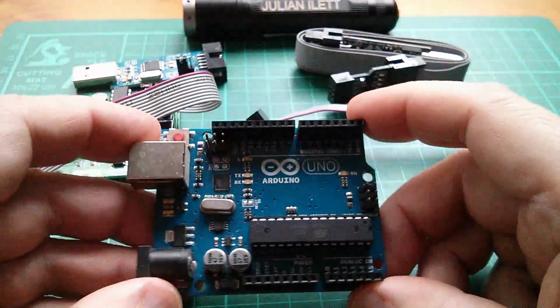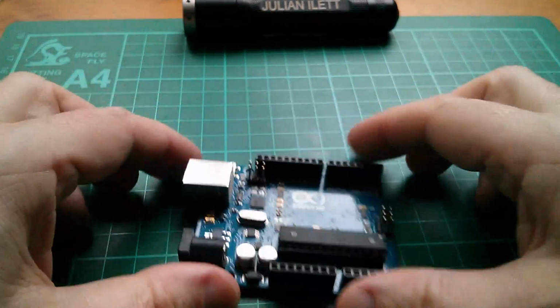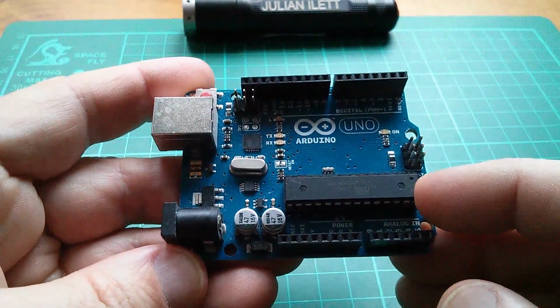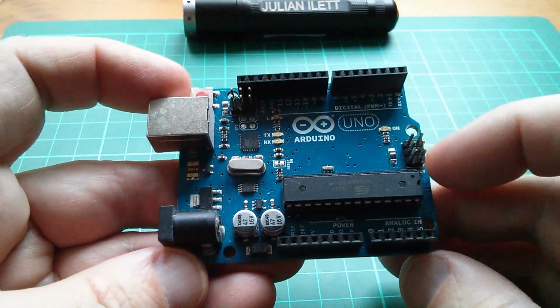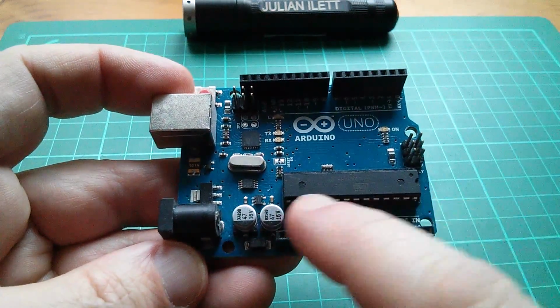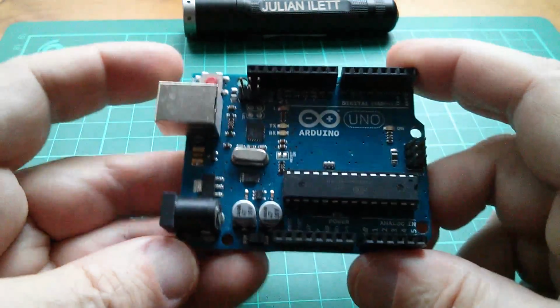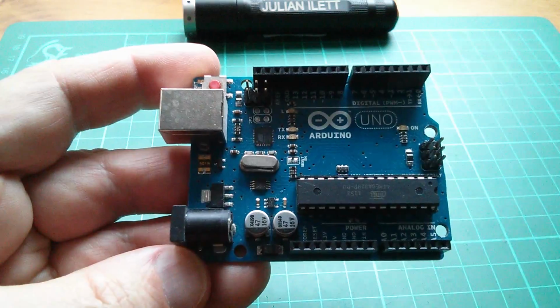Now normally in the world of Arduino we don't use in-system programmers because Arduino has a thing called a bootloader in the chip which wakes up, says, hey, are you sending me a new program over USB? If so, I'll load it into most of my memory, but not, of course, overwrite the bootloader. So we don't need in-system programmers for day-to-day Arduino programming.